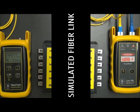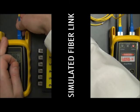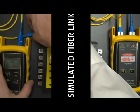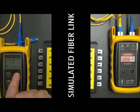So the first thing we need to do is put our patch cable back into our power meter here. Okay, and then just to keep things consistent and organized, we'll test at 1310 nanometers first. To do this, simply press the lambda button so that both units are set to 1310.